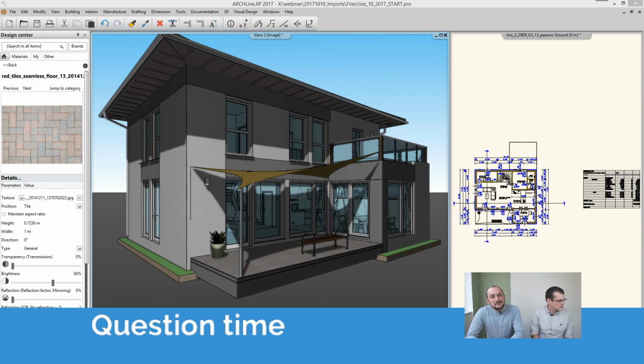Well, lighter, not necessarily. It really depends on the content, but the way you can handle the two different file types is different simply because of the content that they have. Now, you remember we mentioned that a Revit file is a BIM file, and the DWG file is a CAD file. The difference between the two, I don't know if I highlighted that, but now I will, is that when you import a Revit file, you import not just the drawing, you import the building itself with all the information in it. And if you import the DWG file, it is likely only the 2D data. And it's just lines, right?